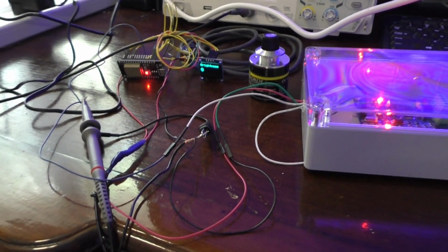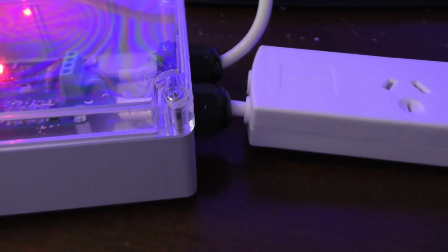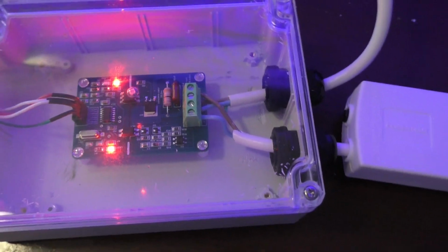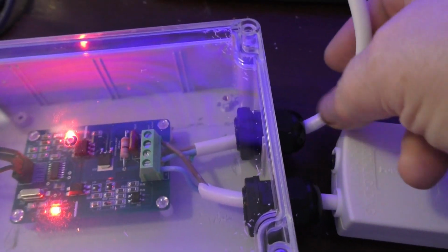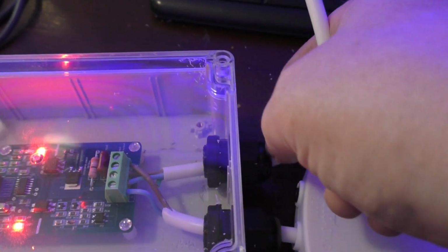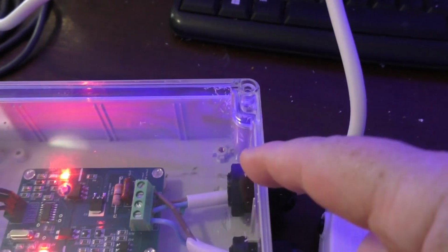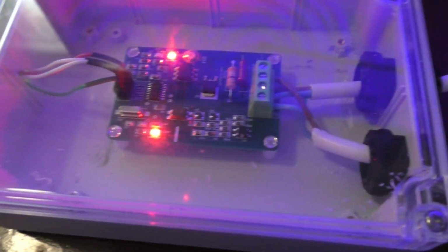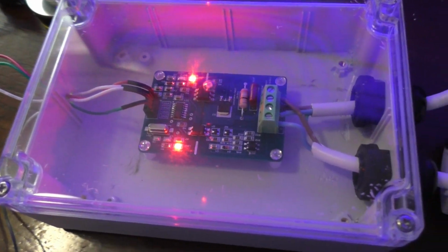And that's about it. So the things to look out for is beware the dangers here of the high voltage if you're going to be doing that, and make sure everything's insulated in some kind of housing with this plastic. It doesn't have to be this big, of course. And make sure that the lead has got something to stop it when you pull it. Otherwise you could pull it out and then you've got a live lead coming straight from the mains, which isn't a good idea. There's probably even better ways to do it than I've done it, but for a brief demonstration, that's about all we need.